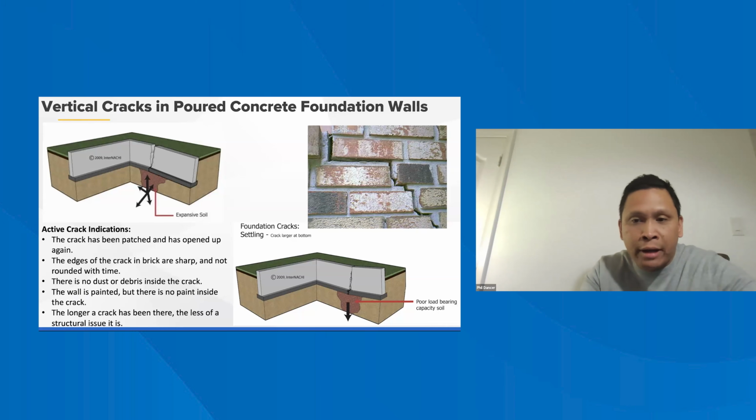So diagonal cracks over windows could indicate a weak header. Diagonal cracks in a poor concrete foundation that are fairly uniform in width, or a hairline type caused by shrinkage, are typically not, as discussed, structural defects, even though they could allow water to transition into the home.